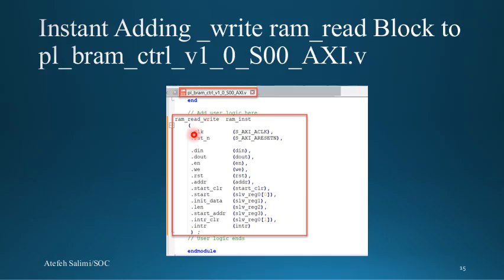And then you have to port map them with the different IO ports of that module and the new name or ports of the top module, which here is S00 AXI.